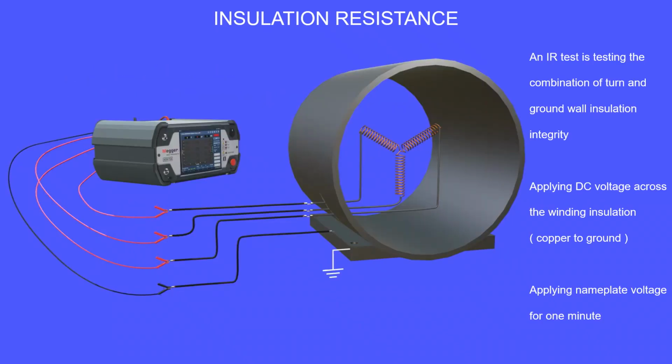IR testing is measuring the ground wall insulation, ground being the actual stator core made up of laminations.